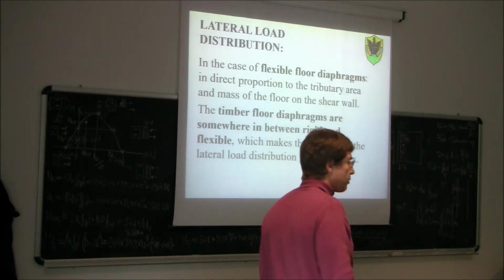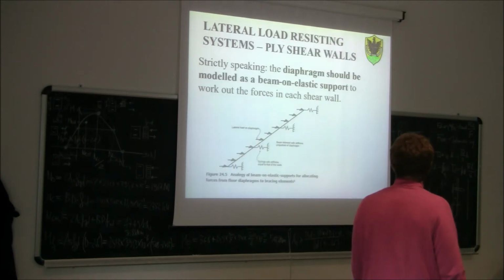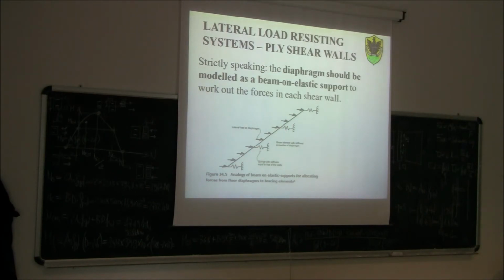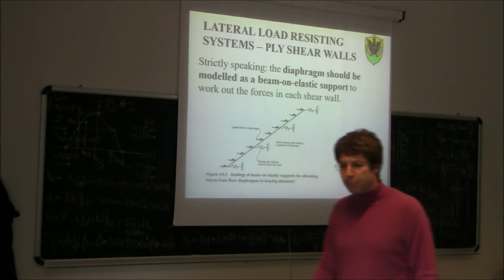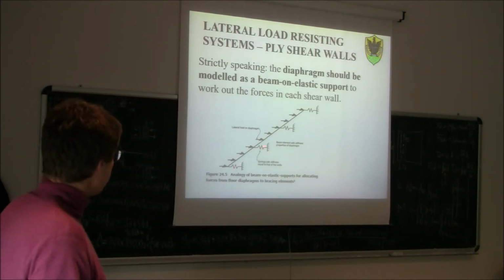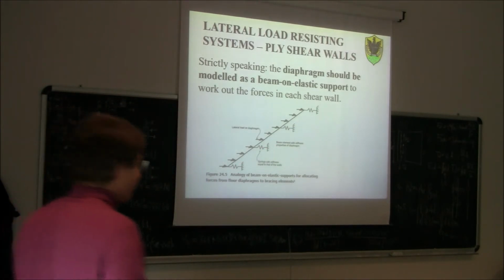So what we need to do is find some kind of simple solution. For example, if I want to account for the in-plane flexibility of the timber floor, how should I do it? Well, I should model the vertical shear walls with a spring, schematizing the flexibility of the wall.